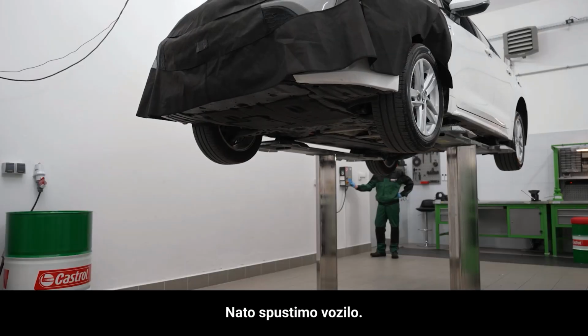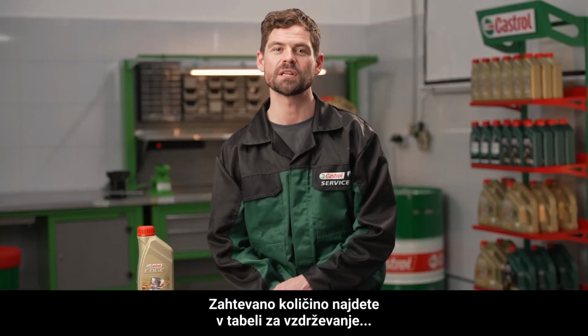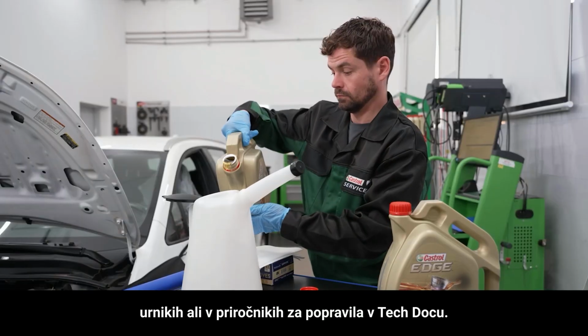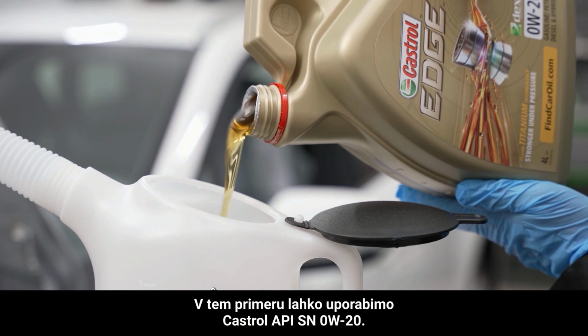We then lower the vehicle. Now it's time to fill the oil. You can find the required amount on the maintenance schedule table or in the Tech Doc repair manuals. In this case, we can use Castrol API SN 0W20.